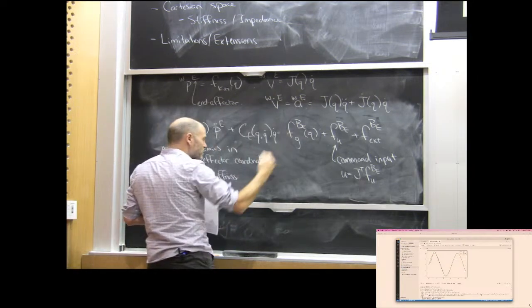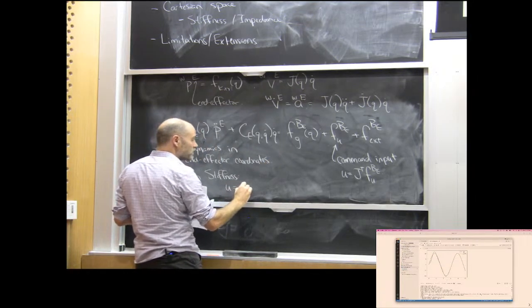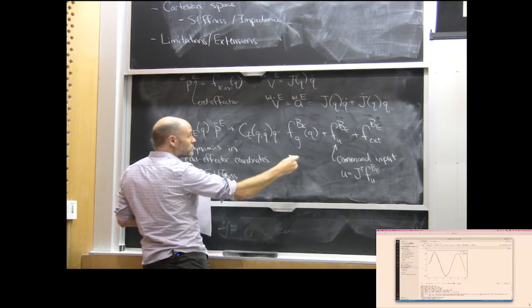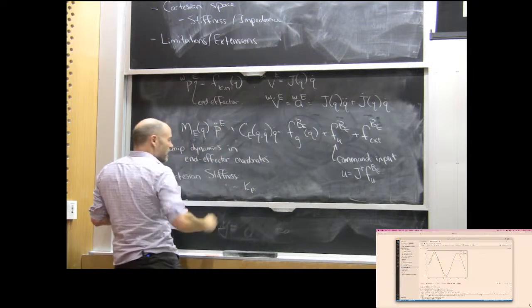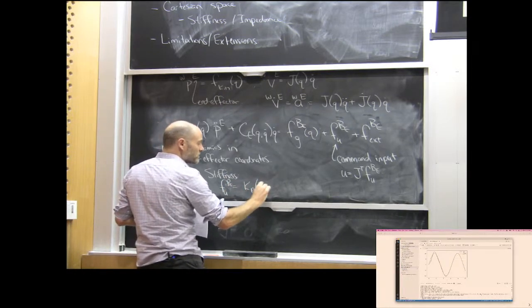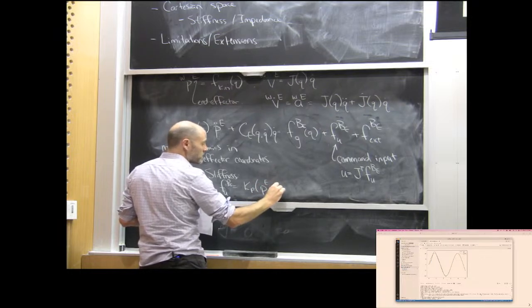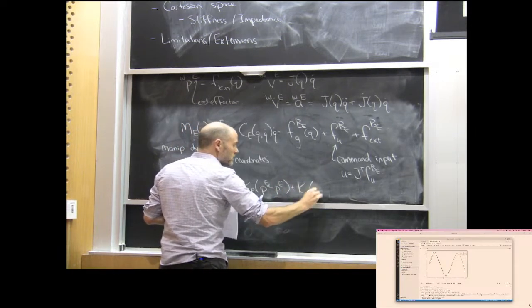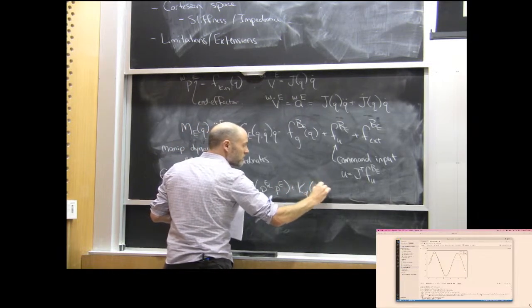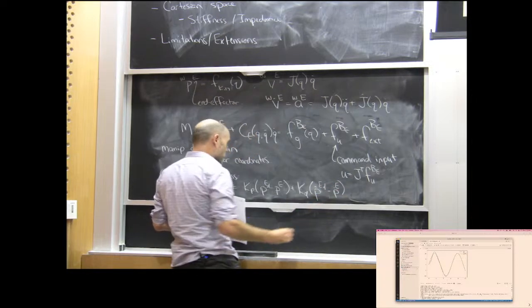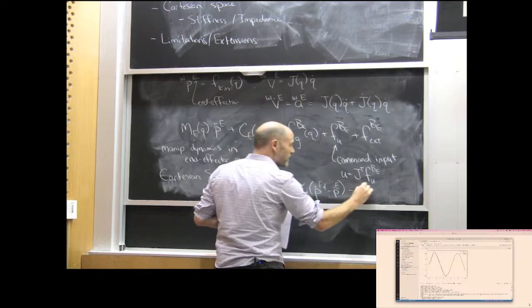This is the analysis, but the controller is simple. It's still just my KP. I have to modify it into the correct space, but in this coordinate system, the controller is simple. I'm going to write it as KP times desired P_E minus P_E, plus KD times desired P dot E minus P dot E, and then minus this F of gravity.